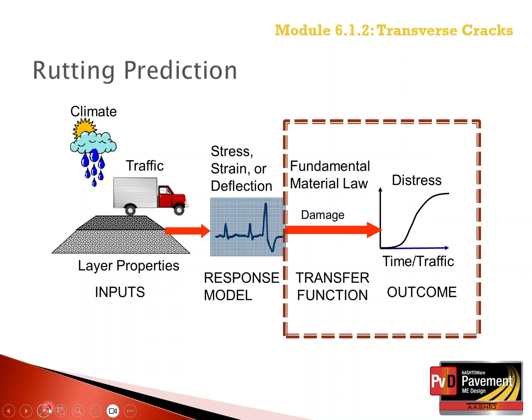The primary response is a tensile stress at the surface of the asphalt wearing surface from low temperature events. In addition, the tensile stress intensity factors are also used as a damage value to predict the length of transverse cracks.